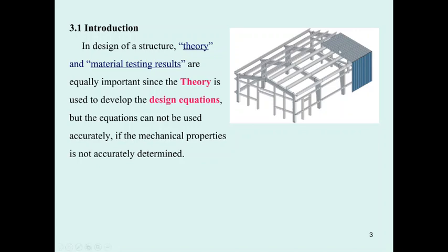Okay, when you analyze this beam, if you set it up as a simple support beam, you can find the reaction. Then you can draw the shear diagram and the moment diagram, and you take the maximum shear and the maximum moment to design the section of the purlin. That is the theory behind the analysis of the purlin.